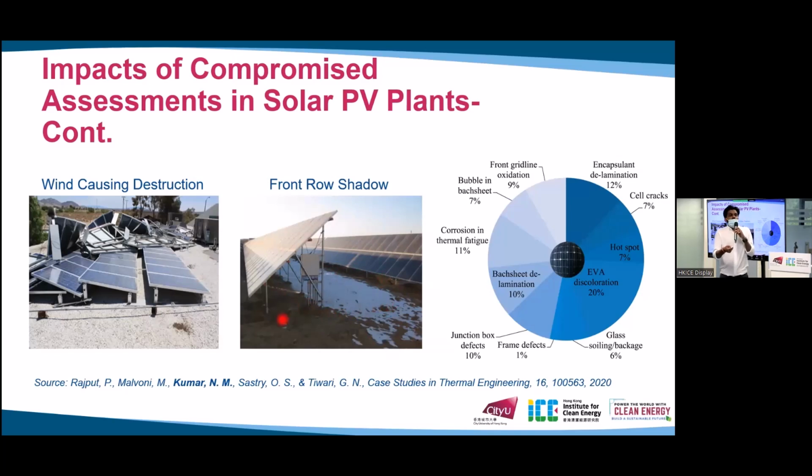So now, what could be the best solution here is to increase this space. If you increase the row spacing, there are already studies that mention that we can get 3 to 5% of excess power. But as you keep on increasing this, the social scientists are coming with a problem of land use conflicts. They say 1 hectare typically comes with 5 megawatts. As you increase the row spacing, the land utilization rate is really high. So this becomes another problem.